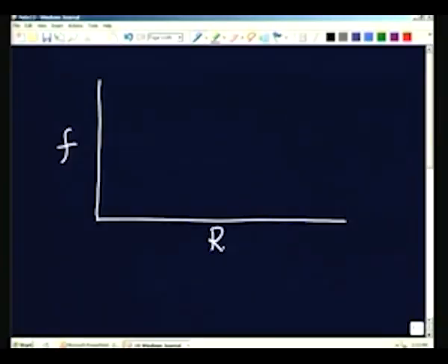That is a great advantage in this particular thing, and therefore, what I will do normally is to choose the diameter as a representative diameter, take a suitable length so that the delta p is not very small, I can measure it easily. Then I vary the velocity over a range such that I cover the entire range of Reynolds number. And in fact, by doing an experiment of that type, we get a plot of the following type. It is just qualitative, I am not going to give any numbers here. For small values of Reynolds number, it more or less goes linearly, and at about greater than about 2000, suddenly there is a change in the value, it goes up and then it goes like that.